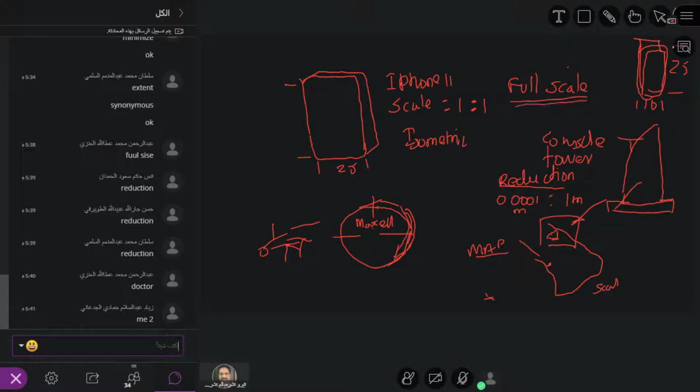This is extremely important for engineers to remember, and that's how you can read the drawing. And always, with the drawing you can measure it. You take the drawing and measure this distance, and if it is 1 mm, then in the original shape you multiply with the scale. If it is 100 to 1, then 1 means 1 by 100 in the original size.